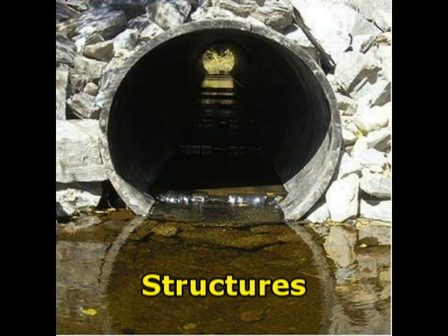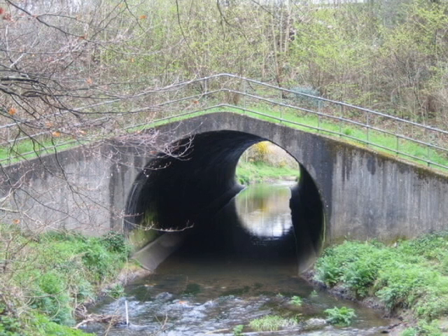Structures. In the selection of a specific structure, the depth of flow D should always equal the depth of flow in the ditch, and the structure capacity should equal or exceed the design flow capacity of the ditch. Standard structures should be used wherever possible. If a special design is required, the job should be designed in cooperation with someone having the authority to approve it.